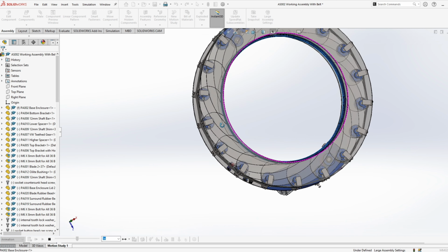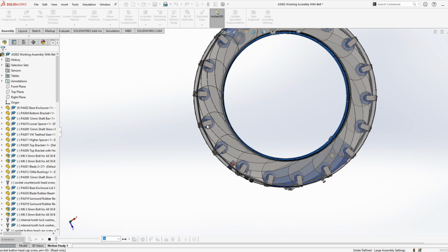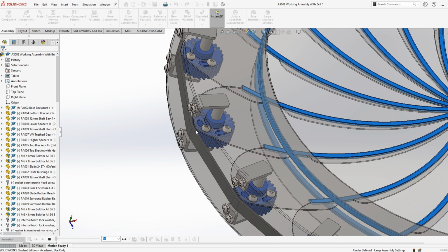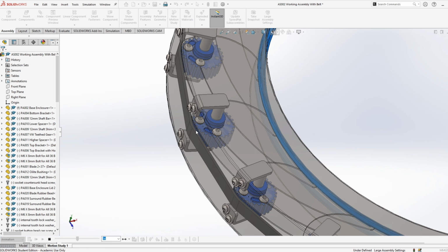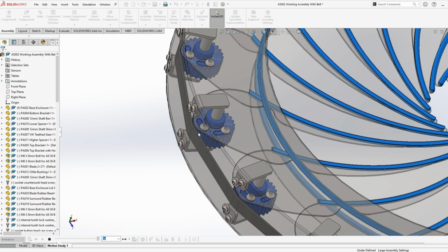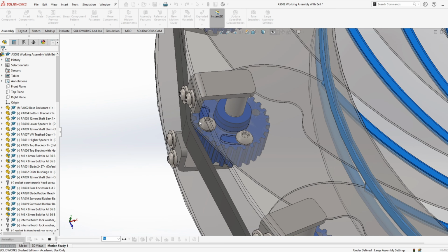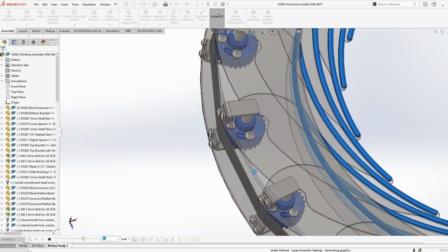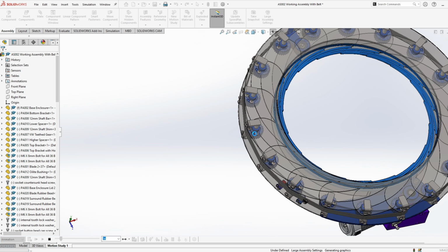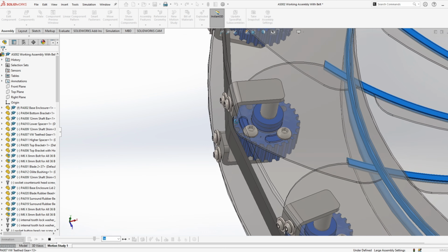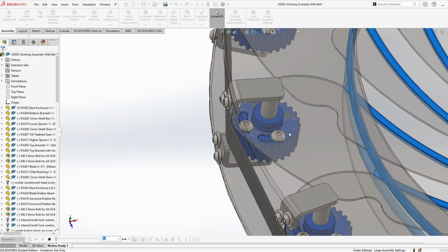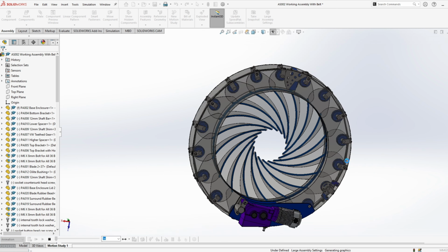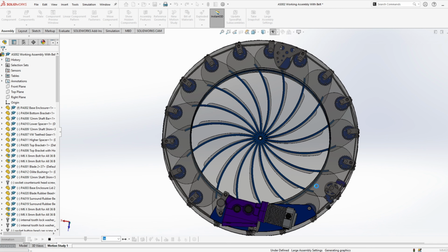Going back to the belt, the way it rests upon each gear: if we look closely here, obviously I haven't got the teeth drawn into the belt. I've just got a band drawn to simulate the belt on the aperture. But if you look closely, due to the close proximity of the other gears and the large circumference of the aperture and belt, we can see that only 3 teeth will be on the gear at any time. So it's important for the belt to be tight. That's really important, so you don't get slippage, or the whole thing will go out of timing.